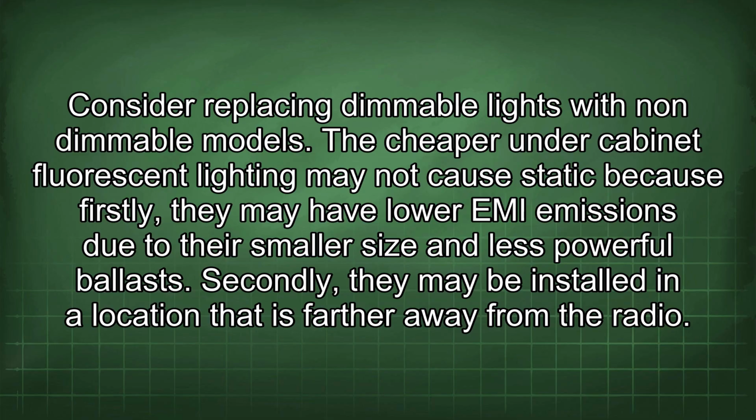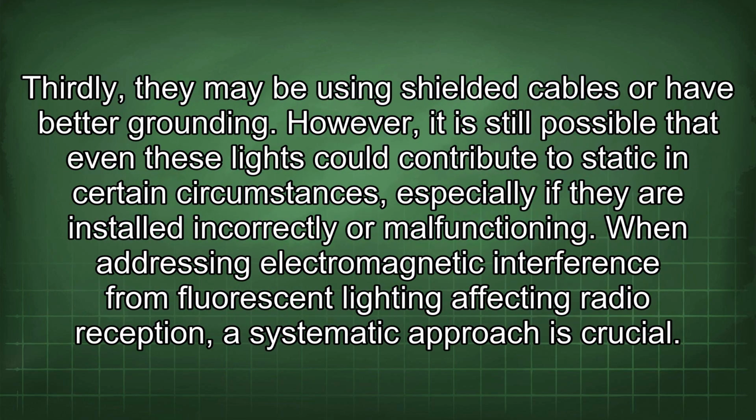Consider replacing dimmable lights with non-dimmable models. The cheaper under-cabinet fluorescent lighting may not cause static because firstly, they may have lower EMI emissions due to their smaller size and less powerful ballasts. Secondly, they may be installed in a location that is farther away from the radio. Thirdly, they may be using shielded cables or have better grounding.